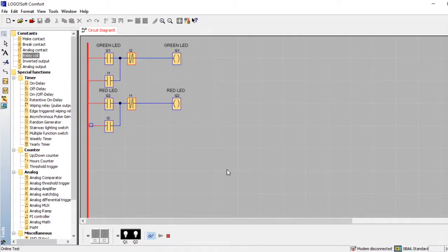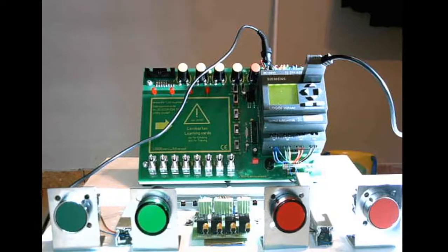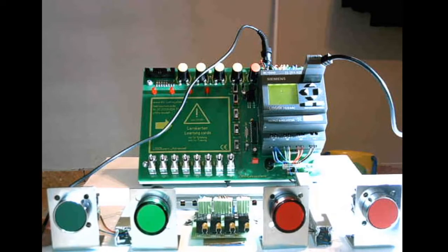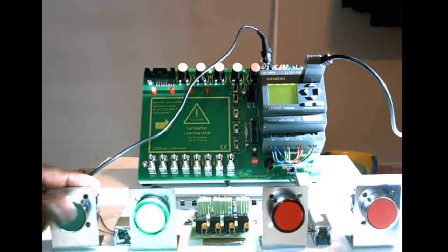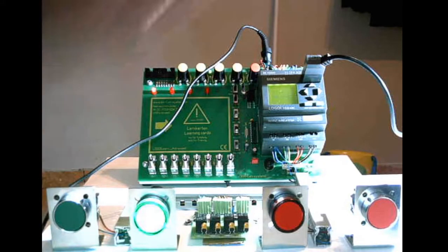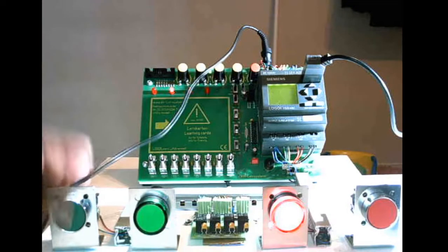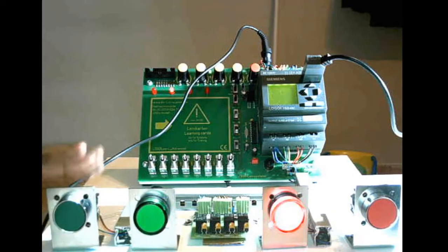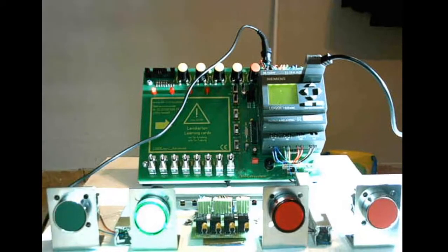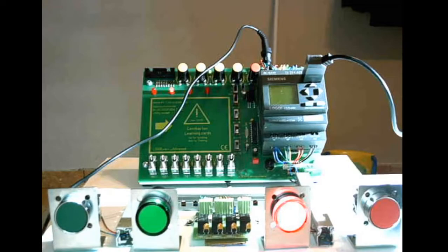Okay, so now we are back again. When I1 is pressed, Q1 is on and Q2 is on in that case. Okay, so this is perfect. Let me therefore demonstrate this using the display. Now when I press, the green LED goes on, and when I press there, the red LED goes on. So this is just a start-stop circuit that runs infinitely like that.